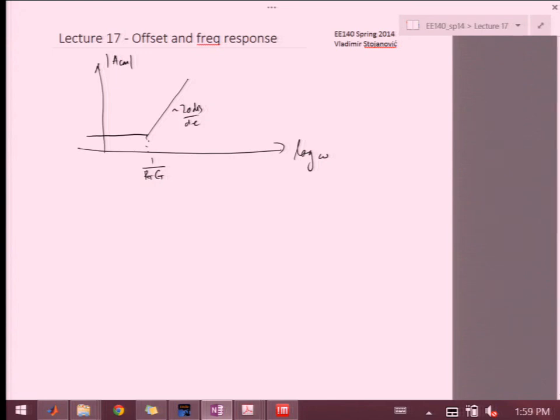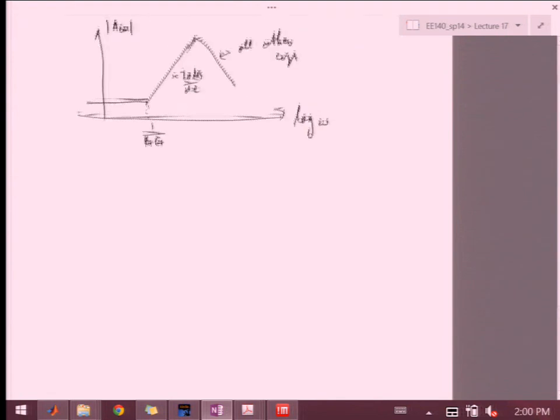It's just the gain is actually, the common mode gain is increasing, right? This is up until the point where we start getting all other caps to kick in, right? So there's all these other caps that will kick in and essentially give us the 2 poles that will shave it off, right? But before then, we were going to get to this 20 dB per decade increase in common mode gain. Now, why is that bad?